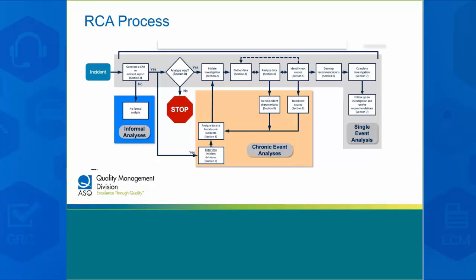In initiating the investigation, we're going to pick our team, we're going to pick our investigation leader, and the people that are going to help that person, okay? Hopefully, during initiate the investigation, we're also going to think some about the analytical scope of our investigation and the physical scope. From an analytical standpoint, I like to point out things like big catastrophes, okay? Fires and explosions, releases of material are all consequences of some catastrophe in a chemical plant.